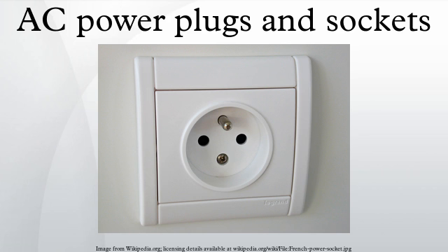Unearthed sockets. Round unearthed sockets have no earth provisions and consequently have been phased out in most countries. Countries using the CEE 7/5 and CEE 7/4 standards vary in whether unearthed round sockets are still permitted in environments where the need for earthing is less critical. Some countries prohibit use of unearthed and earthed sockets in the same room, in the insulated room concept, so that people cannot touch an earthed object and one that has become live at the same time.